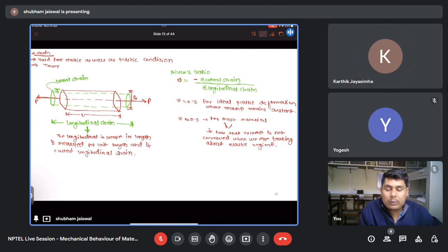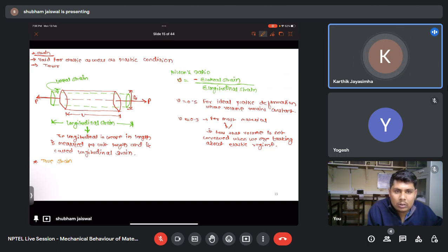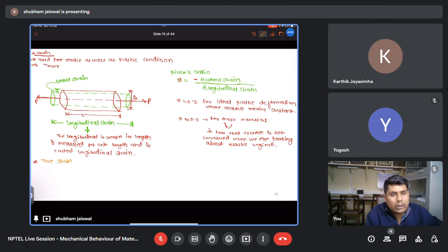Okay. So after that, we have seen the concept of true strain and engineering strain. Sir, 1 second. Now you're telling that a negative sign for the Poisson ratio. Irrespective of whether we are applying the compressive load or the tensile load, that negative sign will take care of the overall change in the material. Yeah, it takes care of sign convention, because Poisson's ratio is always positive.